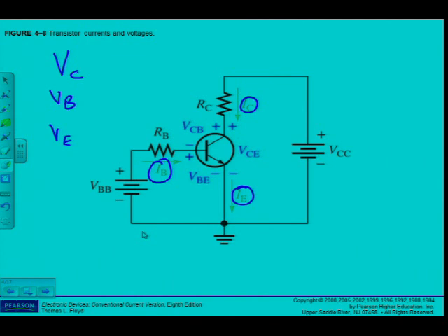measure a voltage VC. Of course you have 2 terminals, a red and a black terminal on your multimeter, and you will put it on DC voltage to measure the DC voltage. But if I ask you to measure VC, you're going to measure it with reference to what? If I have a single subscript letter, what do you do? Of course you will take the red lead and you will put it on the collector. Where will you put the black lead? You always measure with reference to ground.